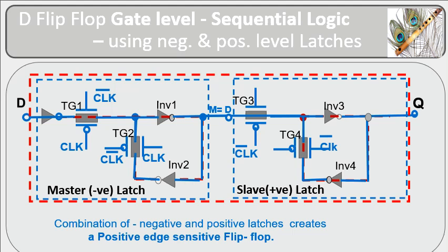The first latch is known as master and propagates the input data D at the clock transition. The second latch, known as slave, propagates the captured data to the output terminal Q. The first latch, the master, with the clock at logic low, operates in transparent mode and captures input data D. The second latch, the slave, with the clock at active high, operates in hold mode and retains its previous data at the output Q. Subsequently, at the next positive clock transition, the latch will operate in transparent mode and be ready to capture the next input data.